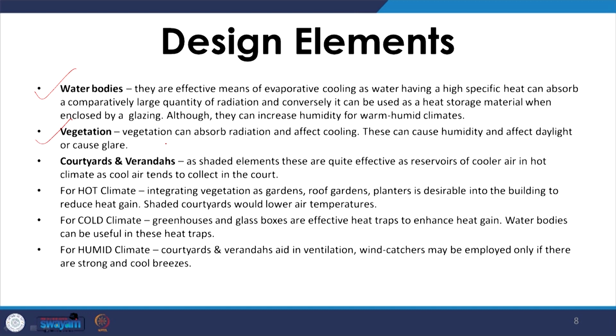Similarly, water body, if it falls en route, the air from where the air is entering into the building in the direction of wind, the air can pick up humidity, moisture from the water body and add to the moisture. So, in a hot dry climate, a water body planned in the route from where the wind is entering the building is preferred, while in a cold climate it may not.